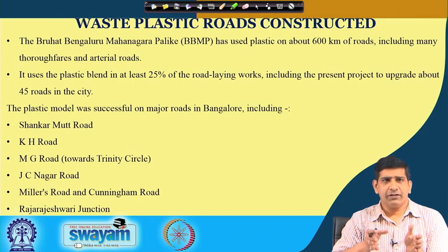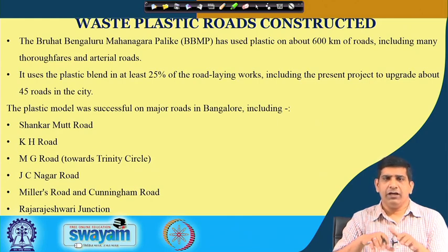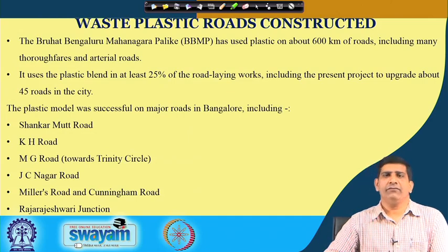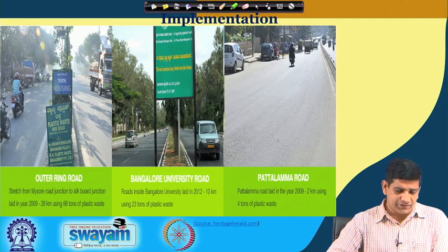It's already being done for the last several years, and this is potentially a good way of managing non-recyclable, non-energy recovery plastic. Rather than sending it to a landfill, we can use it for road construction, because it helps in making the road better. It also helps in conserving bitumen, so you have to use less bitumen if you use waste plastic. The issues associated with microplastics and toxic wastewater should be looked into to make sure we are doing everything okay.